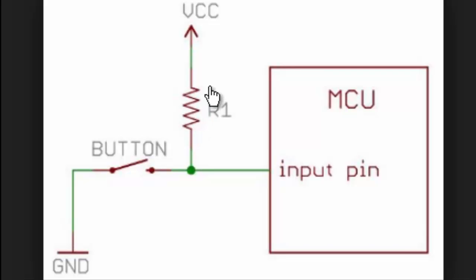in there. So this is all inside the Arduino, and the Arduino is reading all the time on the input pin. And because the current flows to the button, and if we press the button, the current flows to the ground. And at the moment we press, the Arduino reads a different value, and then it knows it's pressed. But the only problem is we have to think backwards, because the Arduino is reading a high voltage all the time, and if we press, then it reads a low value.